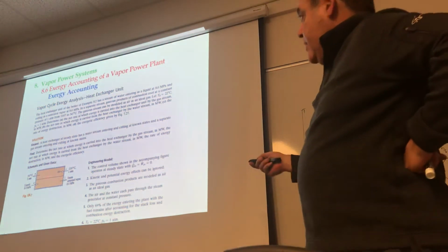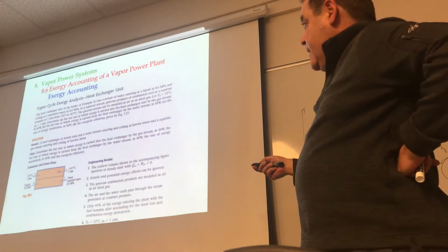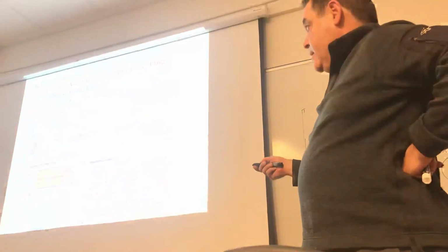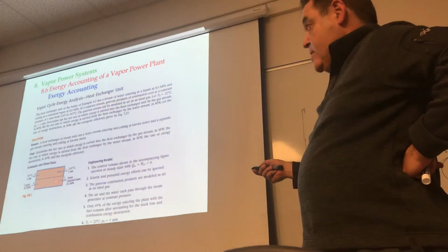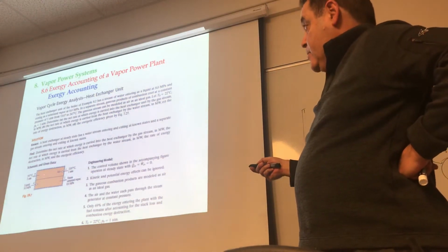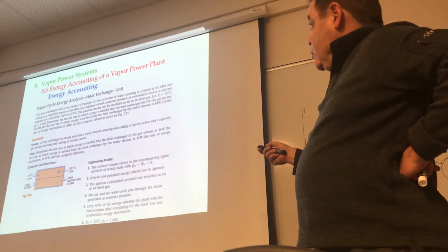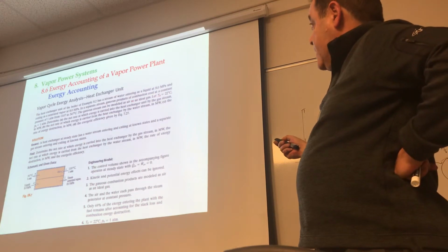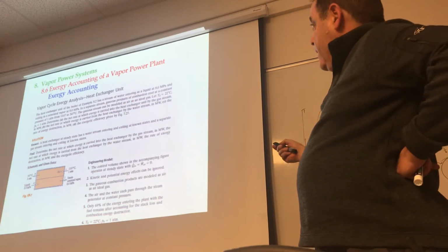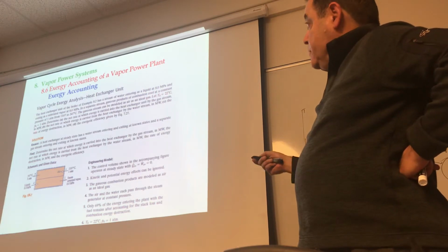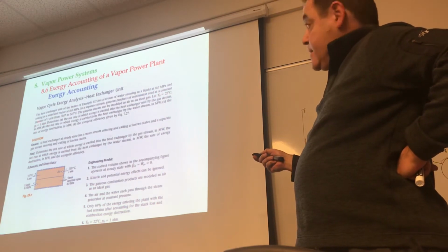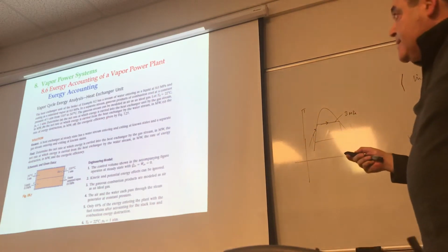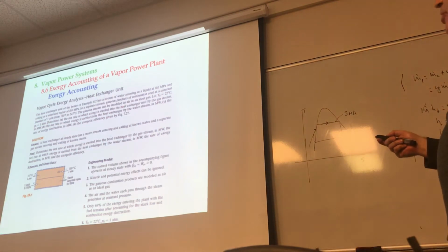because their heat is being absorbed by the water. So in the process, you have water coming in like this, and the air is going through here. The water is only pressurized within the pipes, and here it is just at atmospheric pressure. The hot gases cool. The gaseous stream can be modeled as air as an ideal gas, which is fine. The dead state temperature here is 22 degrees and the pressure is 1 atmosphere. The questions are: what is the net rate at which exergy is carried into the heat exchanger by the gas stream?